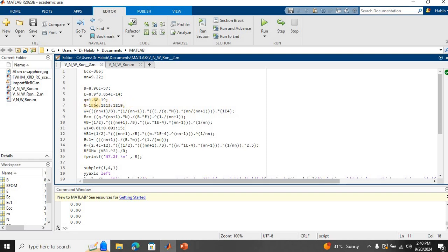This line over here corresponds to the range of doping concentration in per centimeter cube, typically used for the doped N region, like the doped I layer region, in this case for the gallium nitride PIN diode. Gallium nitride devices often operate in this range for power applications. The 1×10^19 is quite on the higher side, but I wanted to demonstrate a range of doping concentration for the I layer.